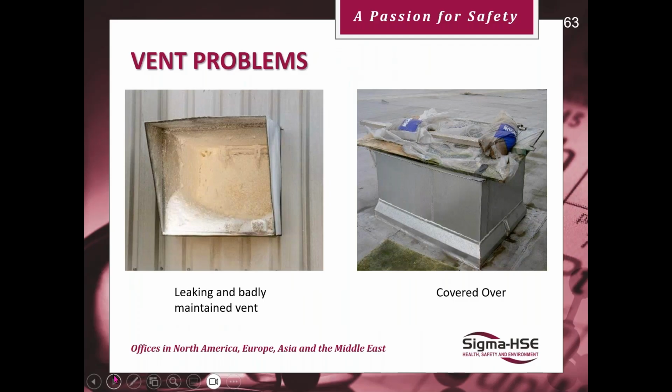Typical vent problems are leaking and badly maintained vents. I've seen covers on top of vents with weights on top, which have become flying missiles if the vent opens. So maintain them correctly.